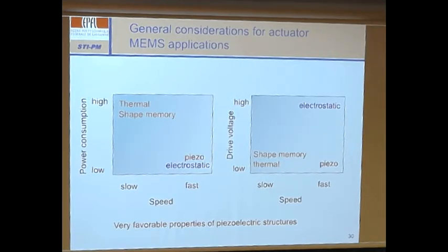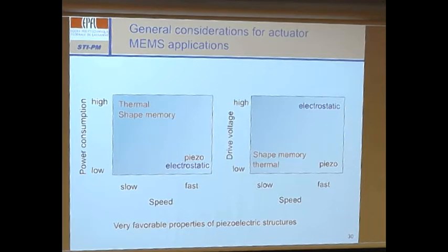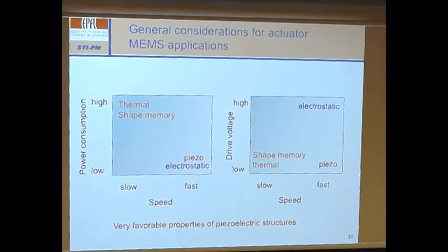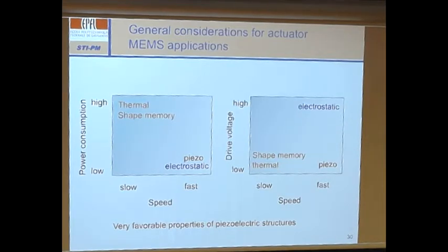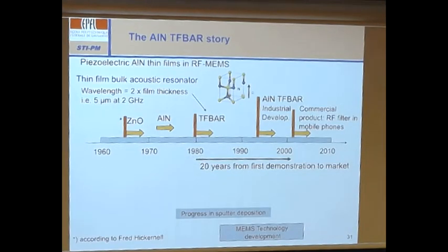Electrostatic also needs much more voltage, because it's basically a very weak effect. You know, it's epsilon equal 1 in electrostatic actuators, whereas PZT is epsilon equal 1,500. And this makes a big difference, and it also reduces the voltage. In fact, electrostatic actuators you don't have in the macro world, because you would need thousands of volts, and this is very dangerous. But in the nano world, if you have a gap of 10 nanometers, you need maybe 10 volts. That's very good. Okay. So you see the advantage, piezoelectrics will never die.